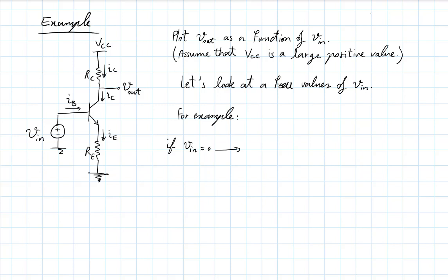What formulas should I use to analyze this circuit? You have to imagine the diode between the base and the emitter. Yeah, so we have this diode here. Just imagine 0.7 volts needed to start really running. Until there, we won't be having much current going through the diode. Right, that's correct. So let's try to write this down mathematically now.